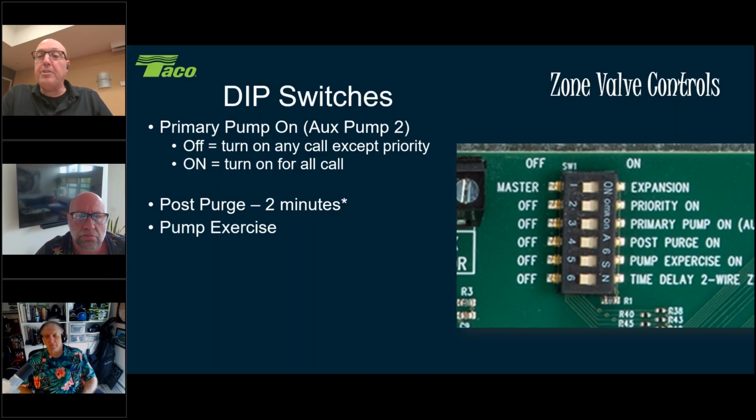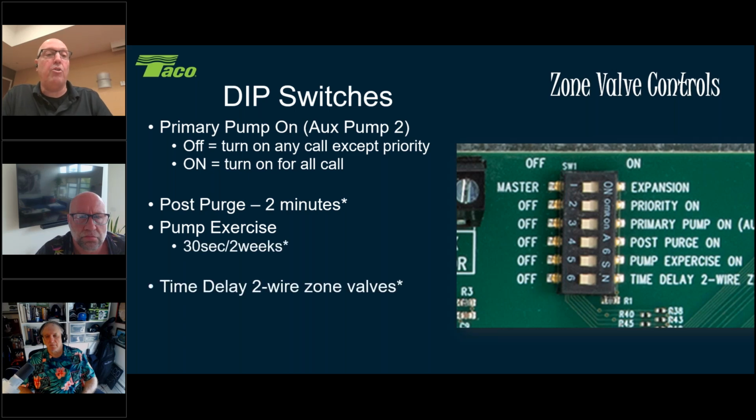You do have your pump exercise here, and then you'll see here also the time delay for the 2-wire zone valves that I was talking about. So that is our last dip switch that we have on the zone valve controls.